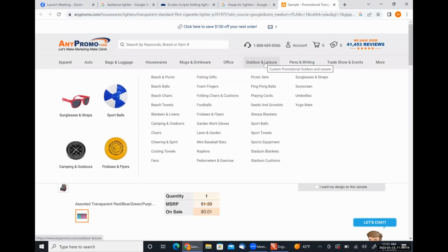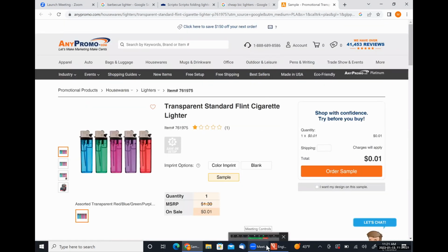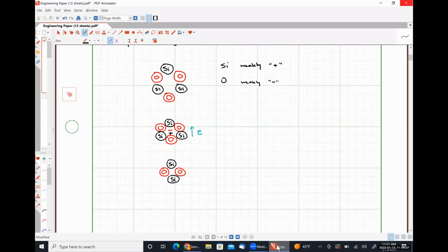Excuse me. Sorry, please can you repeat that statement? I'm sorry, what? The piezoelectric material, like you said, it needs to be polar bonding. Okay, so it needs to have polar bonding as well as point asymmetry, I guess. So not point symmetry, where what I mean by point symmetry is if we went from this point here to this centroid, the thing directly across from it isn't the same material.